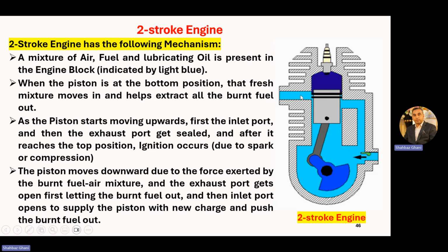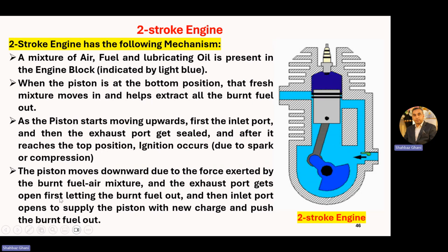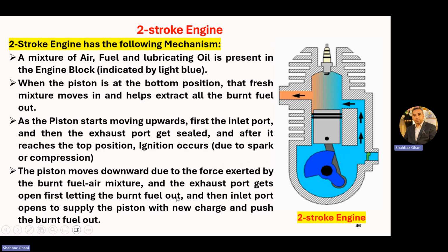So exhaust gases will flow out and the exhaust port gets opened first, letting the burnt fuel out, and then inlet port opens to supply the piston with new charge and push the burnt fuel. First see the exhaust port open, the exhaust gases go out, and then the piston uncovers the inlet port.